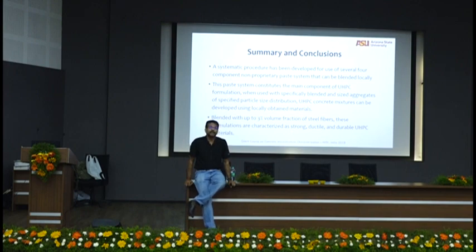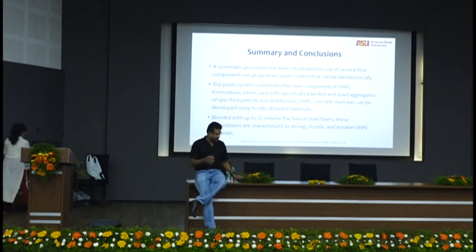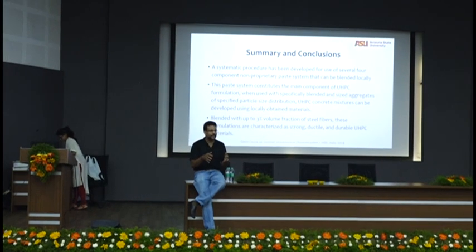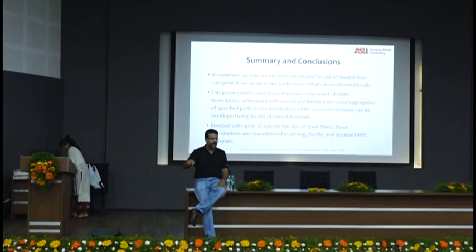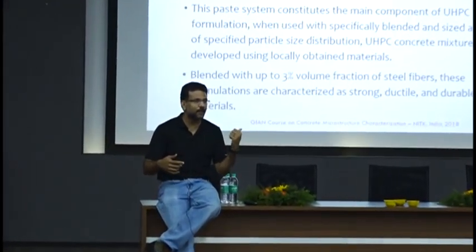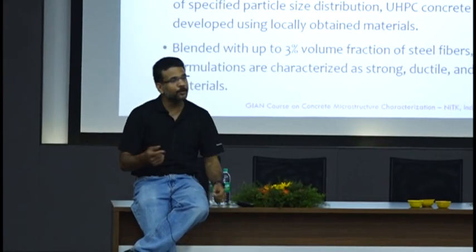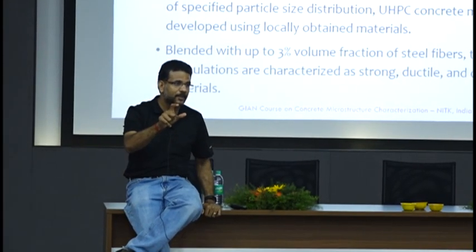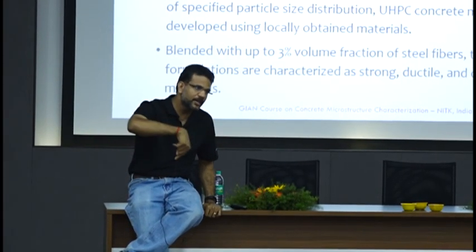Well, at the end of the day, it's not just a speed of mixing. It's a combination of speed and time. Right? And the speed of the mixer also depends on whether you really have a mixer that has speed control. Normally all the mixers that we have are not speed controlled. You have a medium, high, low, and even if you put in high, for a mix that is so dense with little water, it will mix only very slow. So what you want is a mixer that will have power control in the motor, that will give additional power to get you the RPM that you want.